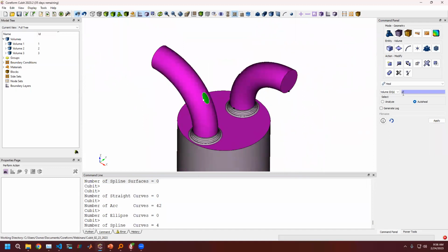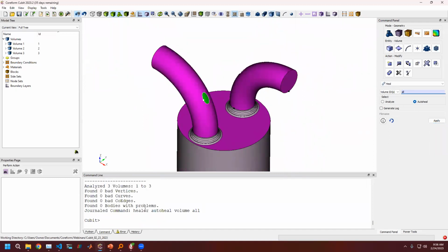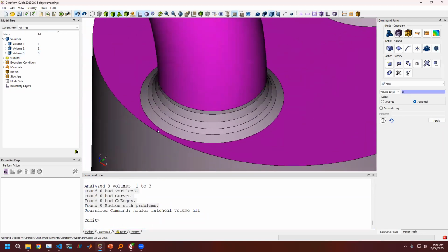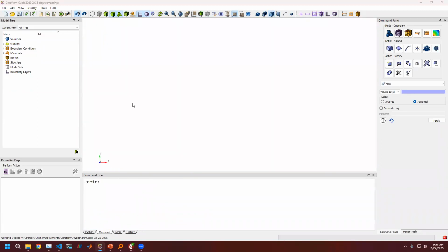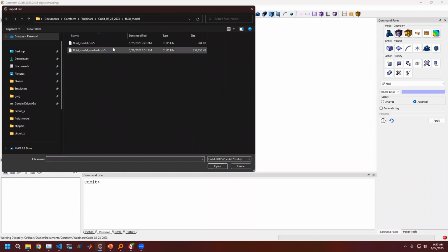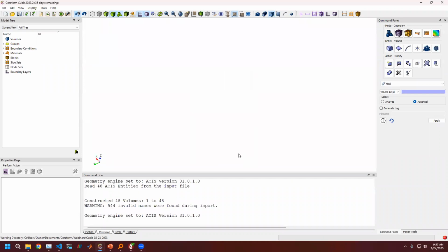now you can see that this model is going to be very well behaved for us because we got a good scale and a lot of analytic geometries. So there's a whole bunch more stuff that we could talk about. If I wanted to proceed with web cutting, I would assign blocks before I start web cutting for meshing. We didn't talk about compositing. We have previous webinars where we've talked about compositing, but just as the last thing to end on, and then for questions, I'll show the final meshed version of this.